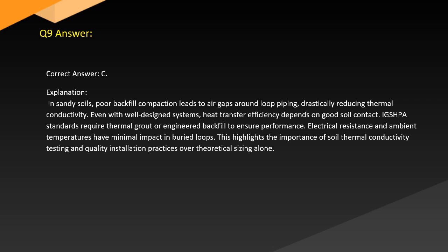Correct answer. C. Explanation. In sandy soils, poor backfill compaction leads to air gaps around loop piping, drastically reducing thermal conductivity. Even with well-designed systems, heat transfer efficiency depends on good soil contact. HVACR standards require thermal grout or engineered backfill to ensure performance. Electrical resistance and ambient temperatures have minimal impact in buried loops. This highlights the importance of soil thermal conductivity testing and quality installation practices over theoretical sizing alone.